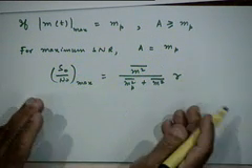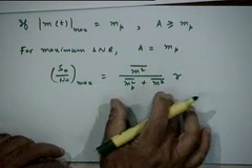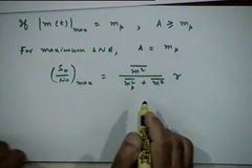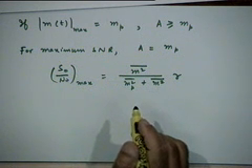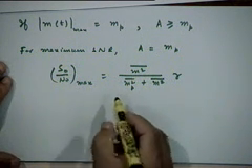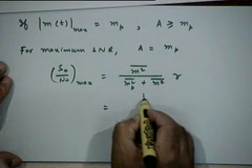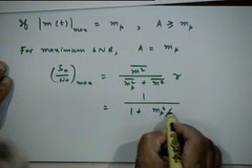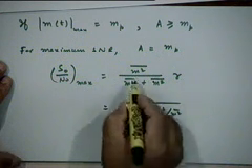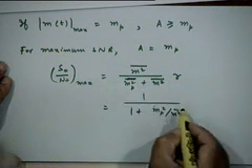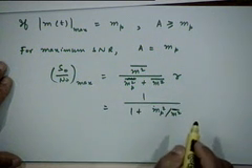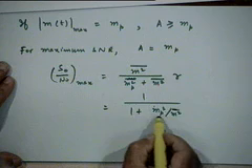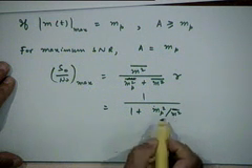So this is an expression for the output SNR in terms of only the message properties, right? Nothing else. And now, if you were to take some typical example, there is one more way in which you can write this. You can write this as 1 by 1 plus m_p square by m square bar, into gamma. Actually, there is no bar here, this is just the peak value. Sorry for that. Now, what will be the typical value of this ratio m_p square by m square bar?